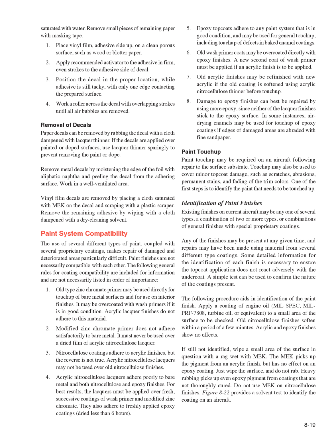The following procedure aids in identification of the paint finish. Apply a coating of engine oil, mil-spec, mil-PRF 7808, turbine oil, or equivalent, to a small area of the surface to be checked. Old nitrocellulose finishes soften within a period of a few minutes. Acrylic and epoxy finishes show no effects.